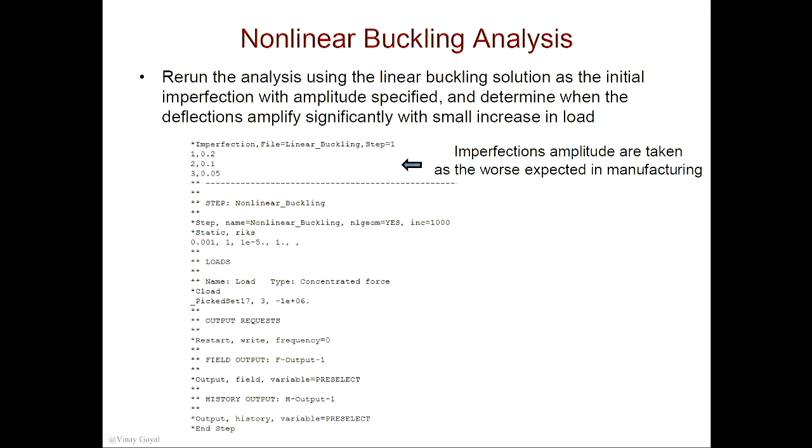That is not going to happen in an experimental environment. But Riks allows you, using this arc length method, to track the solution over load and deflection. Okay, it's able to do that. That's more for a more advanced course, of course, but I think I need to mention that so you're aware of it. Now, we will apply a load of 1,000,000 and then let Abaqus run the analysis until failure happens.